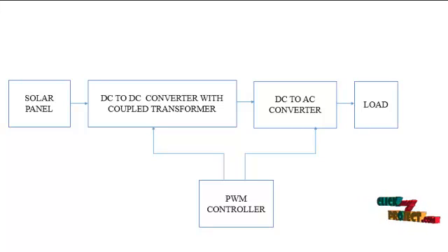In MATLAB simulation we only have a solar array, so we must create a PV module using the solar array. This PV module consists of 72 solar cells connected in series when the irradiance value is given to the solar terminal. The solar cell converts solar energy to electrical energy. A solar cell or photovoltaic cell is a device which generates electricity directly from visible light by means of the photovoltaic effect. In order to generate useful power, it is necessary to connect a number of cells together to form a solar panel, also known as a photovoltaic module.